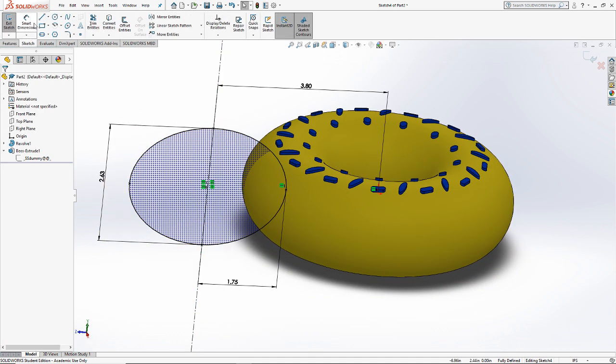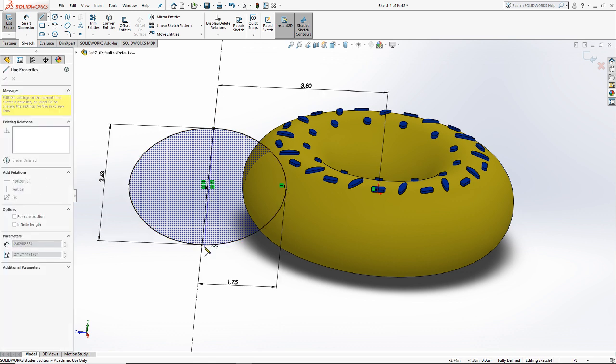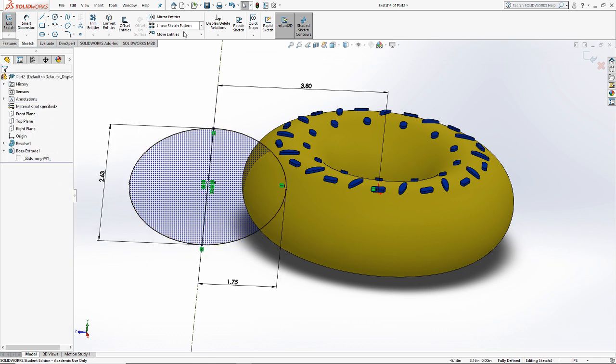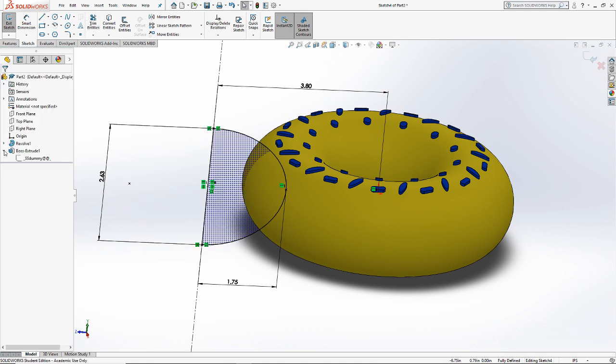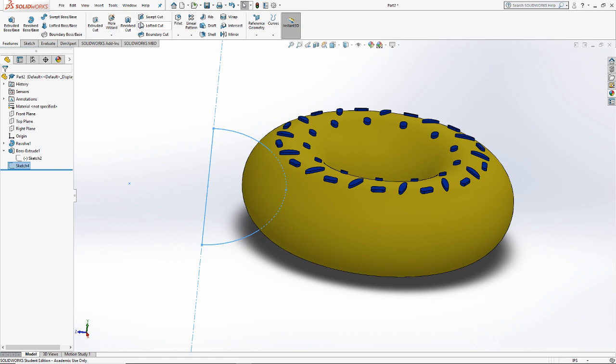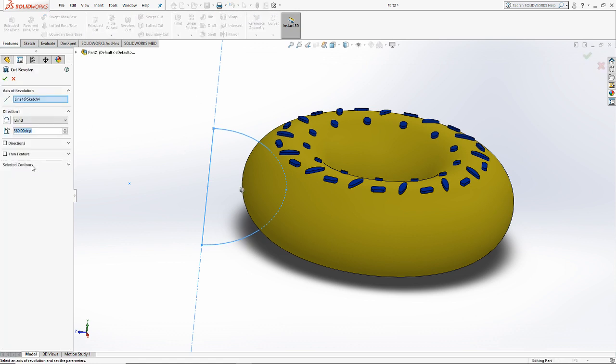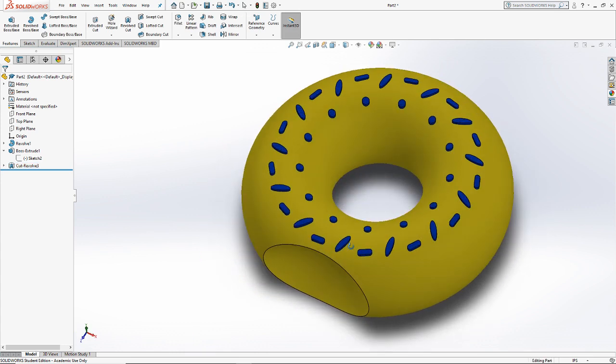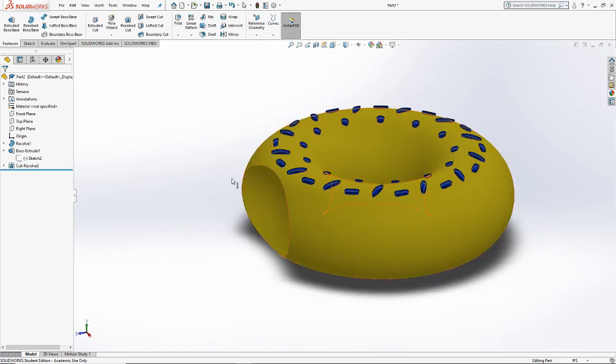that. I didn't close my region. Gotta close your region when you're creating bite marks. And I can trim off the back just so that I don't get confused. So if I go back up to revolve cut, revolve around that arbitrary center line, there, that might look like a more realistic bite mark.